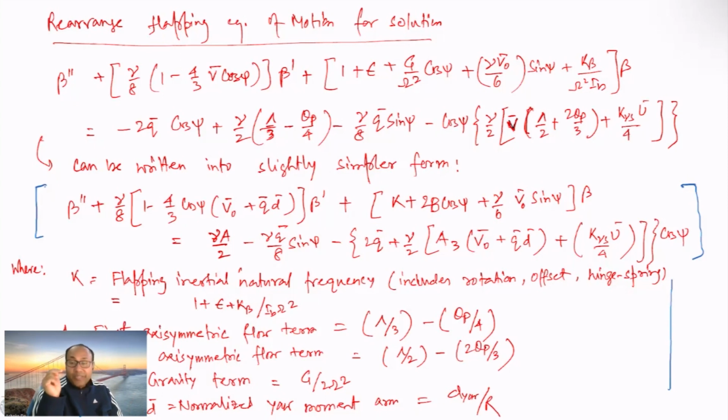As I have said, the free motion could be a special case of this equation if we make the right hand side zero, which is due to the aerodynamic force, I mean, all the forces and moments due to linearized aerodynamic force, and force and moment due to yaw rate.